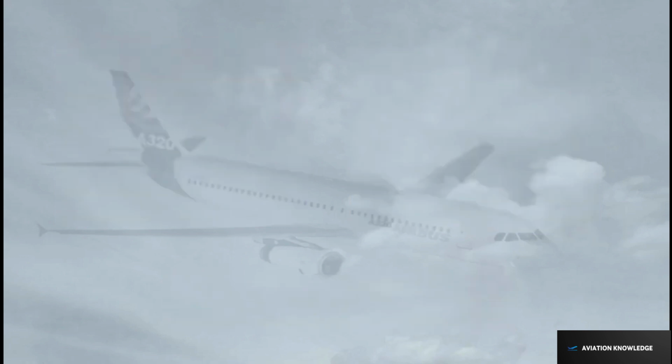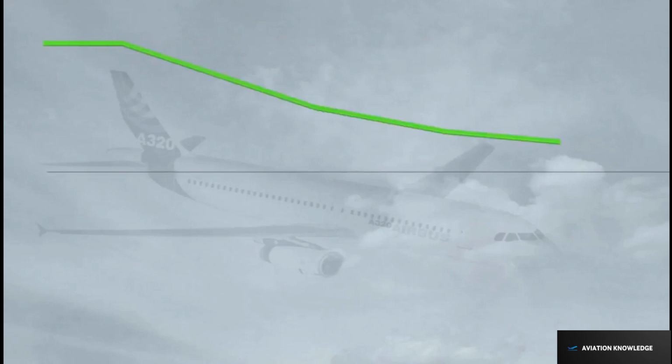The descent mode of the autopilot flight director guides the aircraft along the FMS computed descent path so as to descend to the FCU selected altitude. The descent path includes several segments: from top of descent to the first constraint waypoint, an idle segment, then several geometric segments computed up to reaching 1,000 feet with V-approach.